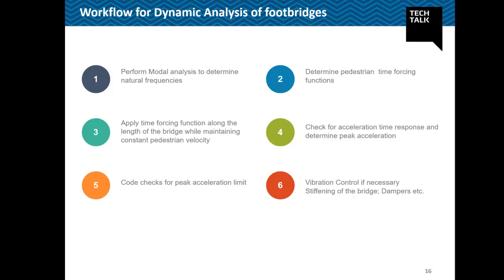on the structure. The purpose of performing free vibration analysis is to find the fundamental natural frequency of the structure, plus what the mode shapes of my structure are. So how my structure is going to be excited, and what my fundamental natural frequencies are. So this is my first step. Using these fundamental frequencies, I will be creating my time history load cases, load functions, and I will be applying those load functions on my structure.